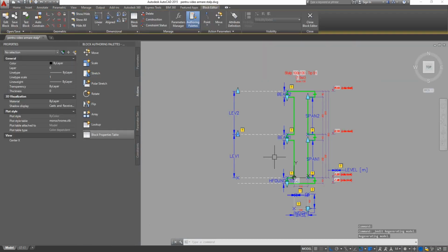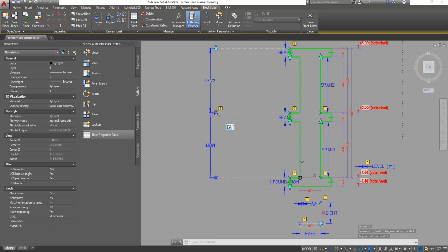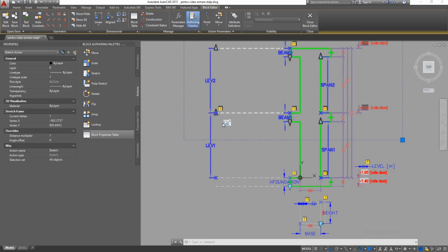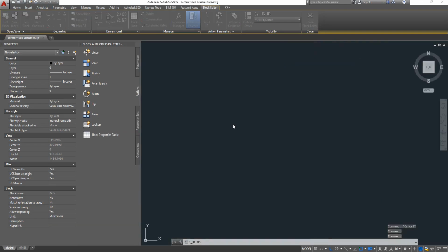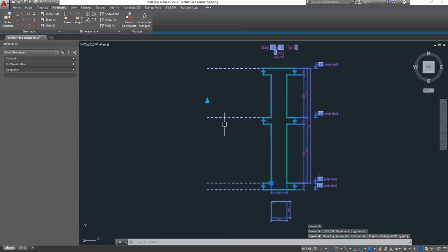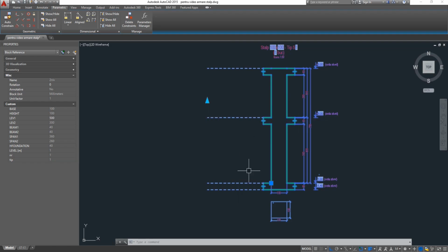if for some reason, there you go, I have to search for the action again, I'm taking this action, click on it, and go to the distance multiplier and hit 0.5, which means half of the value, half of the distance, look what happens. Choosing the block again. So I have the grip that normally should be here at the top of the first level. It still has the designated value 500, but graphically the drawing stretched a little bit differently.